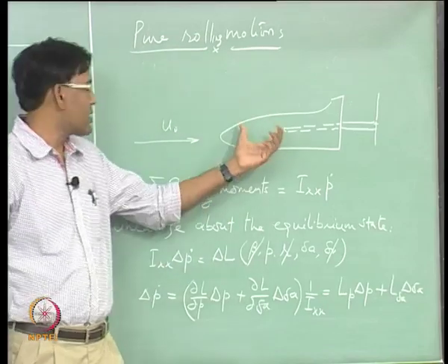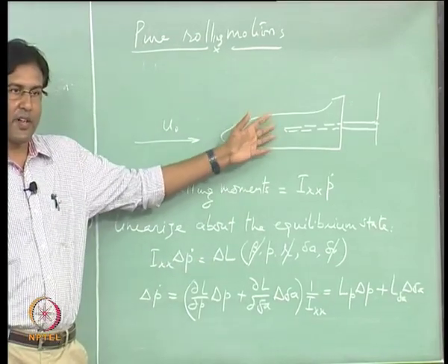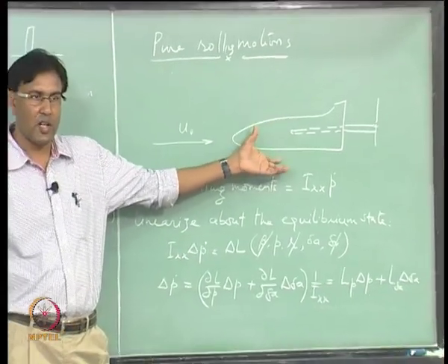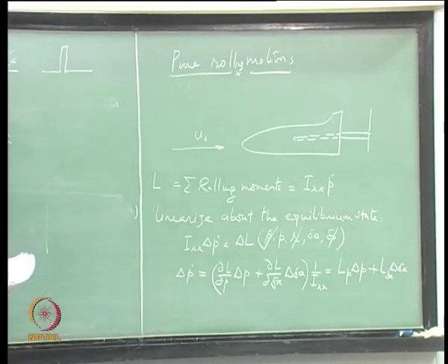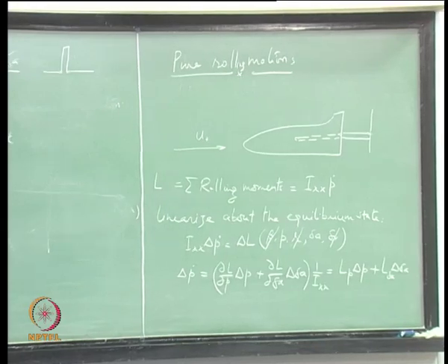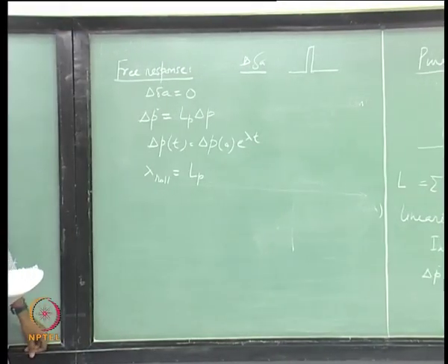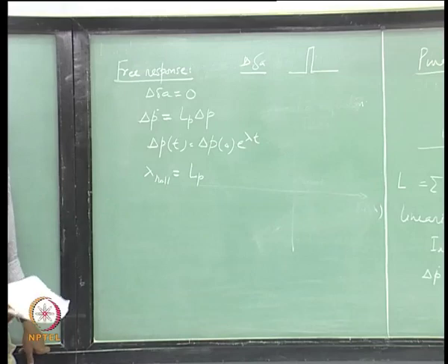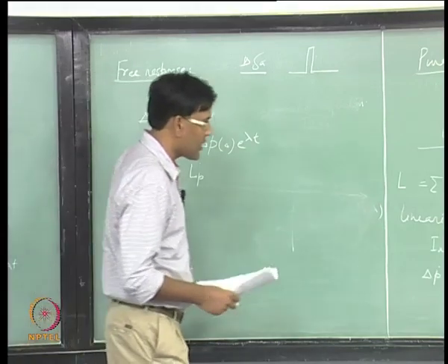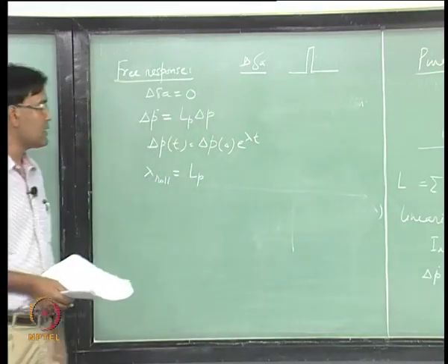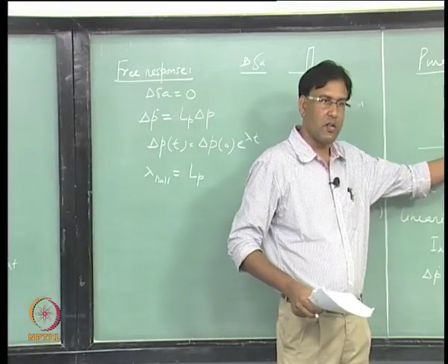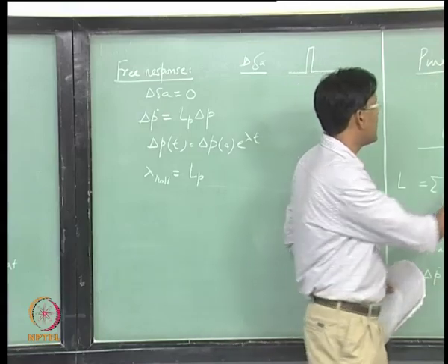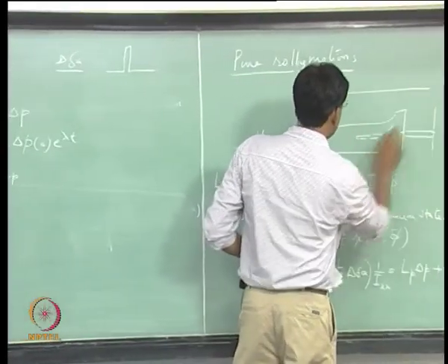Yeah, but yawing is not there, there is no degree of freedom in yaw for this particular model. In flight, yes, it will be always coupled. Whenever you have delta beta, you will have both roll and yaw. But here this model is constrained to have only one degree of freedom in motion, and that is roll.